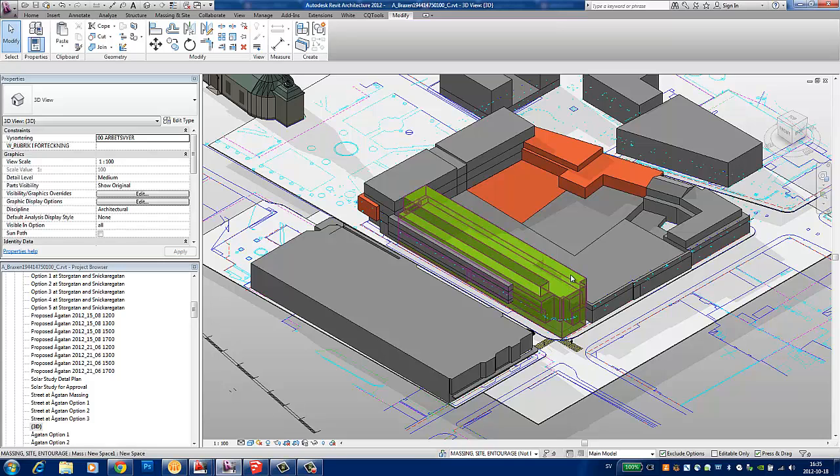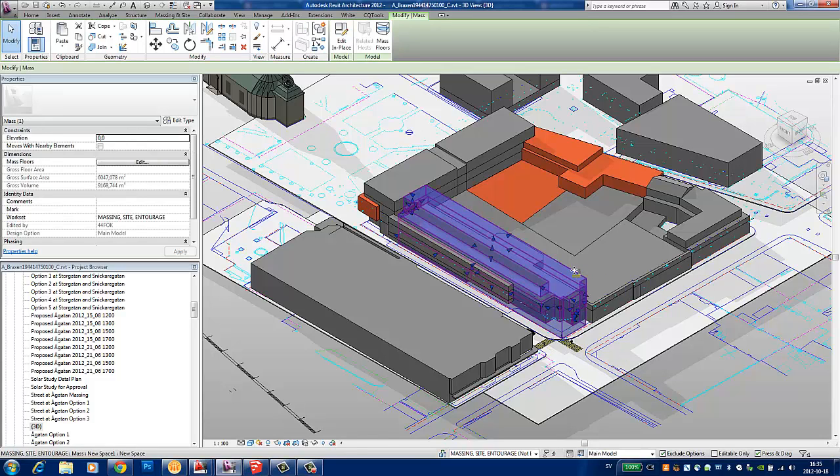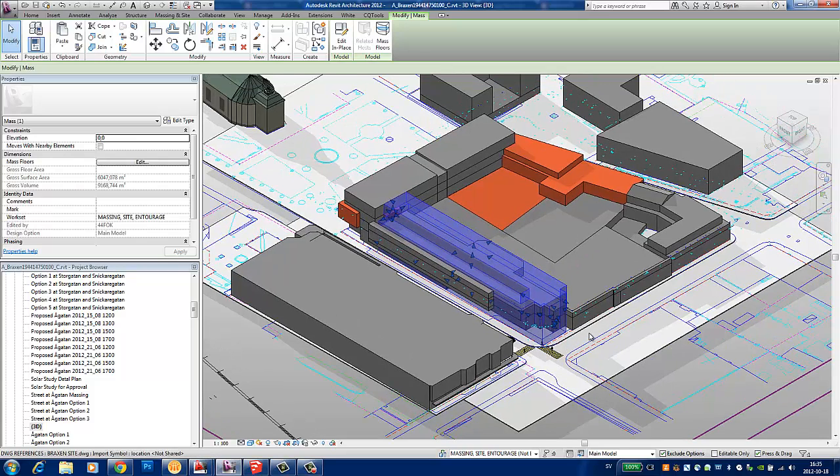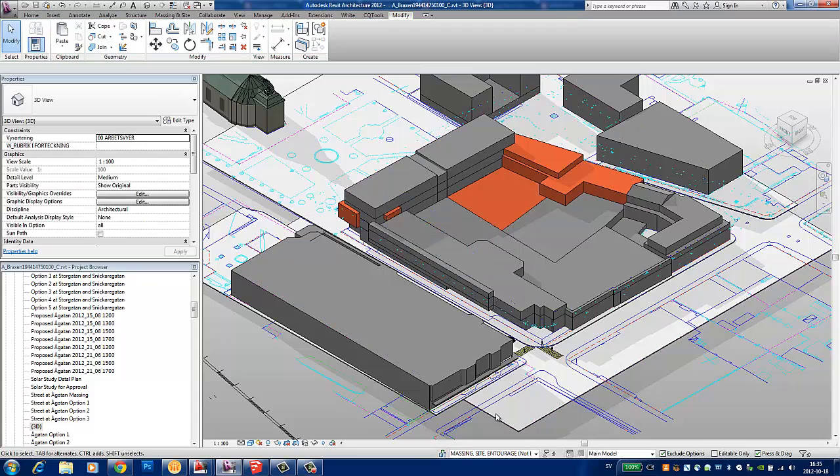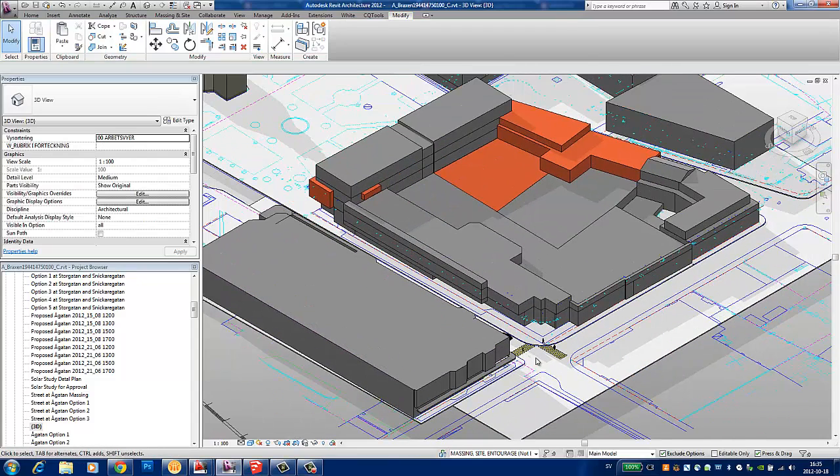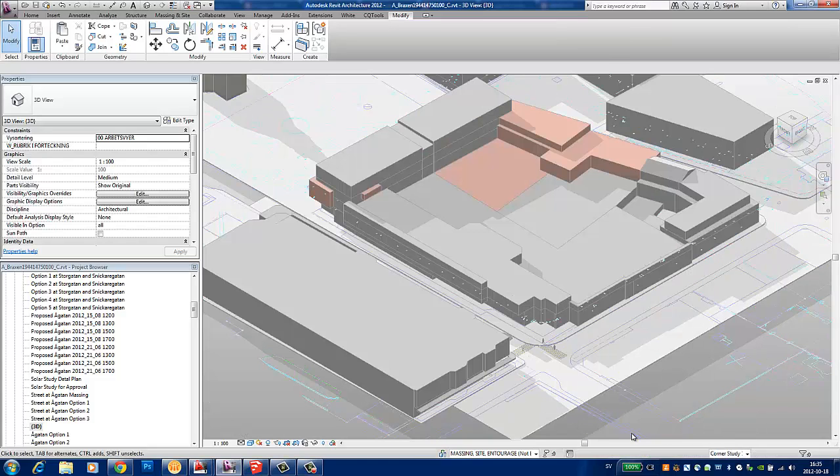Close that out. And so what I'll do here is actually a little strange, but you have to take the element out of the main model. And what I just did was Control X to cut it out. And then I actually want to pick each one of these and come back with paste and go align to the same place.